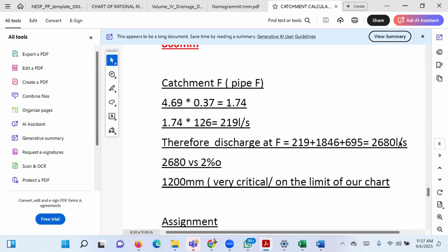So if I should get a value that's above this, I'm going to use empirical value. It means it has gone beyond rational method. It means I have to now do the calculation manually. Or if I'm a very smart engineer, I'll add an arbitrary value to this. Maybe increase it to 1.4 or 1.5 to take care of any excess.